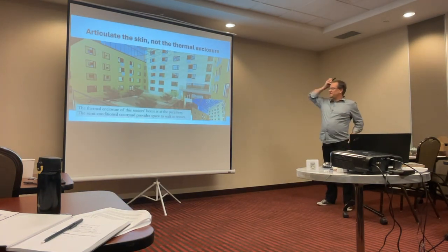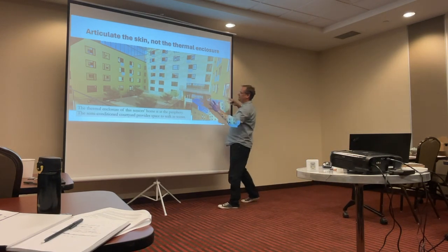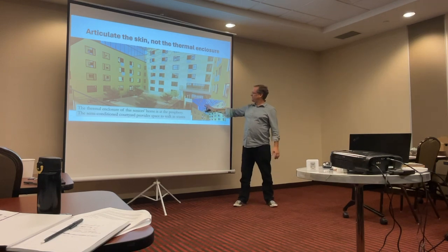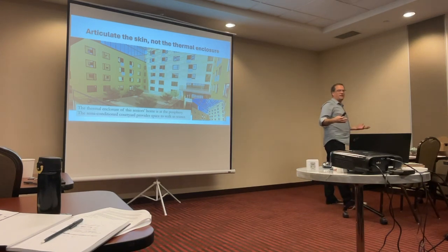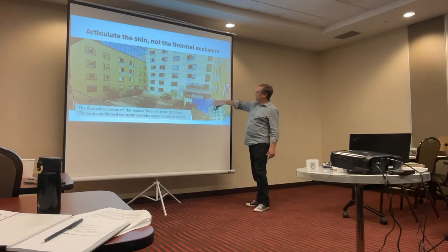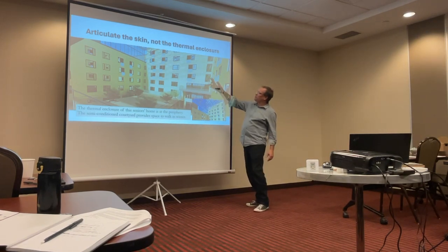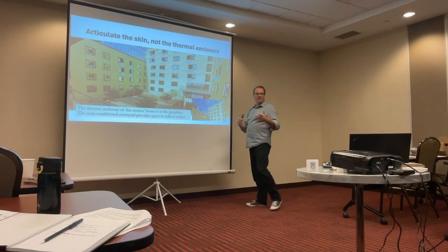Here's another version. This is a Passivhaus, I think in Finland or Sweden. I need to confirm that. Passivhaus project, seniors home, northern climate. It has this big protected area outside the thermal enclosure, so people can get out and walk in winter without the snow. In the winter, they closed this up a bit, so a little bit of warming happening, and the air coming into their HRVs came through the courtyard. In the summer, it opens up, blows out, and the air avoids the courtyard, so they're preheating a little bit.